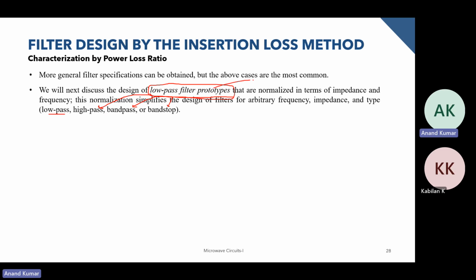This particular prototype will actually be in normalized terms. The impedances and the frequencies will all be normalized. And once you have this prototype, you can just scale it to whatever impedance and whatever frequency you want, and you will have the filter ready.